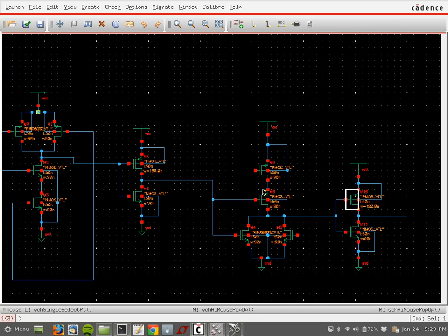Except for, okay, let's look at this case. In this case, I have two PMOS in series. Remember the sizing problem we used to do in 585? When we have two PMOS in series, it's not enough to have double the size of the NMOS. In this case, let's see the effective resistance. So here it's 90.